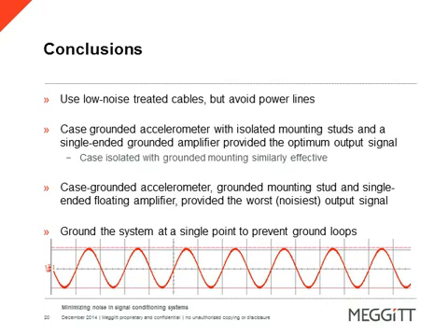We did talk about differential piezoelectric accelerometers, and they have a case-grounded design with a low-noise shielded twisted pair cable arrangement, and that is coupled to a differential charge amplifier. These are all key to minimizing noise in a very tough environment where they're typically used. It's designed to provide common mode noise rejection and designed for these stringent applications, which, without going too much into, is beyond the scope of the webinar. However, similar noise sources and other issues may adversely affect differential accelerometer tests.